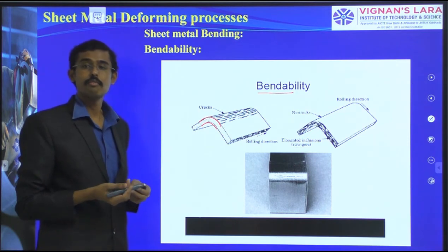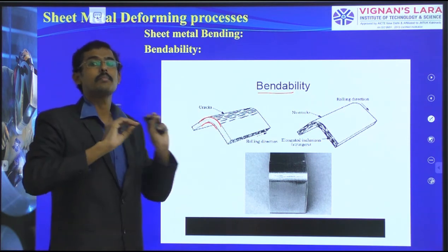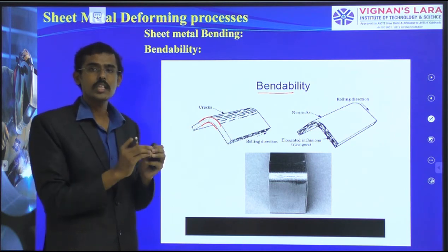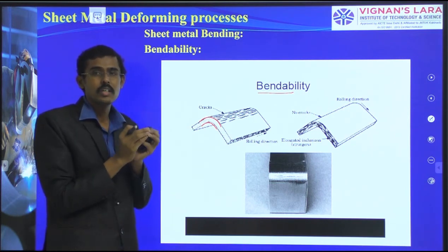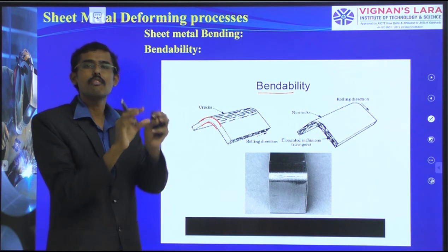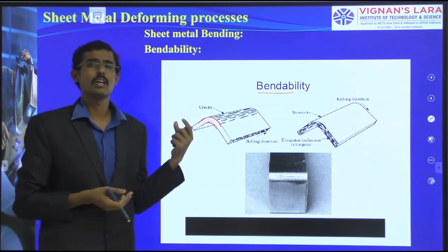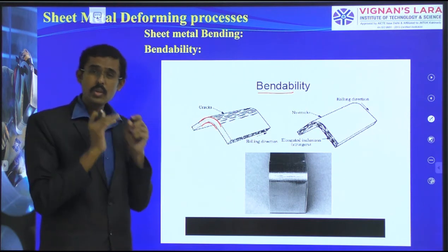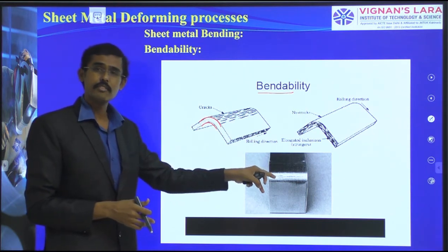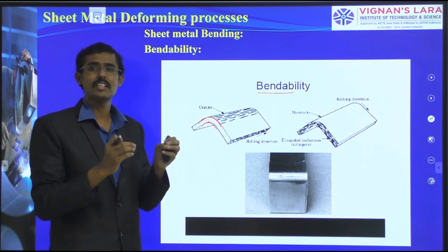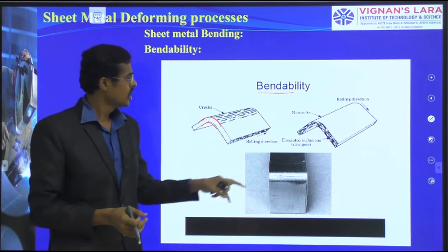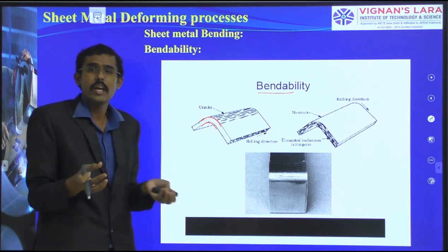Therefore, let us assume we are doing the welding process and we want to check whether this welded component has the capability of bending. Now we are doing the bending treatment through this V bending or roll bending operation. During those processes, if the specimen does not have the strength, the mechanical properties, the weld is going to break.